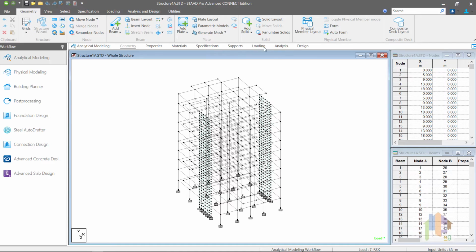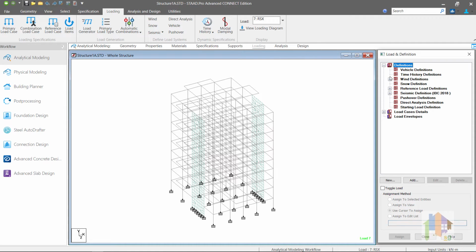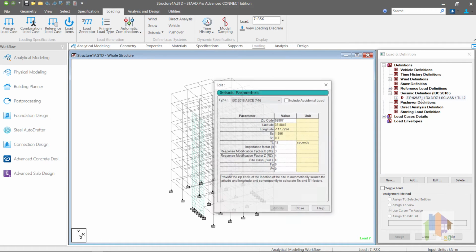For this approach, we are not concerned about different modes and behavior of the structure for each mode. Here the contribution of the fundamental mode is only considered, and on the basis of that, the base shear value is calculated. There are some empirical formulas mentioned in each code which are more or less similar.